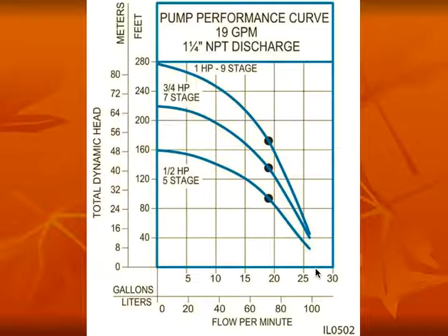So the pump curve, and it doesn't really matter which pump model you use. This particular one's for a Flint & Walling 19 gallon a minute turbine pump, an Orenco P20 pump, or an A.Y. McDonald 20 gallon a minute pump, which are all going to have very, very similar pump curves. But this is going to be our, in a sense, limiting factor for design, the capability of this pump under this curve.